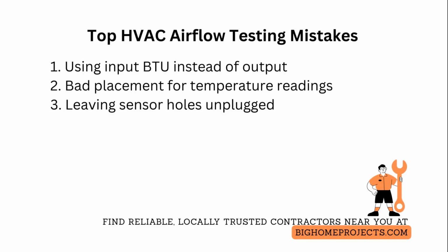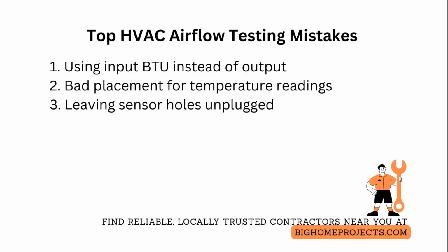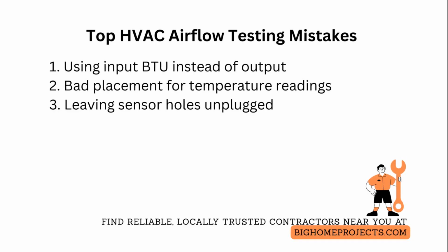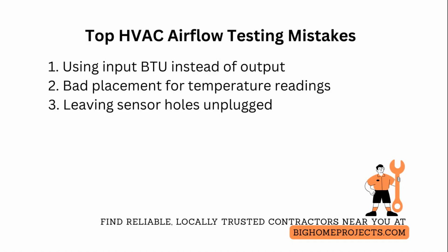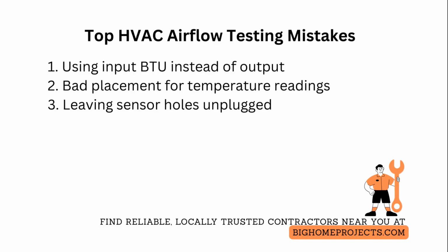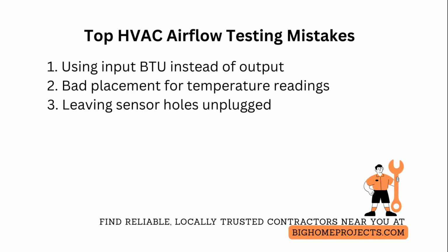The third frequent issue in heating airflow measurement is forgetting to plug sensor holes, which creates duct leakage, depressurizes rooms, and corrupts future temperature and static pressure readings. Fix it by sealing holes right after testing, using metal screws and approved mastic or foil tape over a metal patch to fully restore ductwork and improve indoor air quality and energy efficiency.